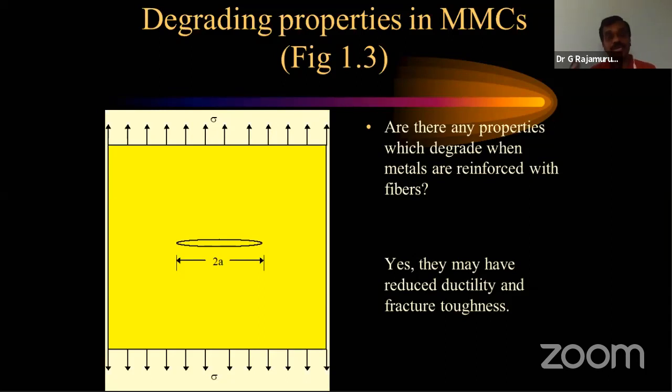Intergranular crack will propagate through the grain boundary, whereas in transgranular crack, the crack will propagate through the grain. But this is for engineering material. Whereas in composite material, the particles don't have any bonding between each other. It looks like such bonding, but basically there won't be any.